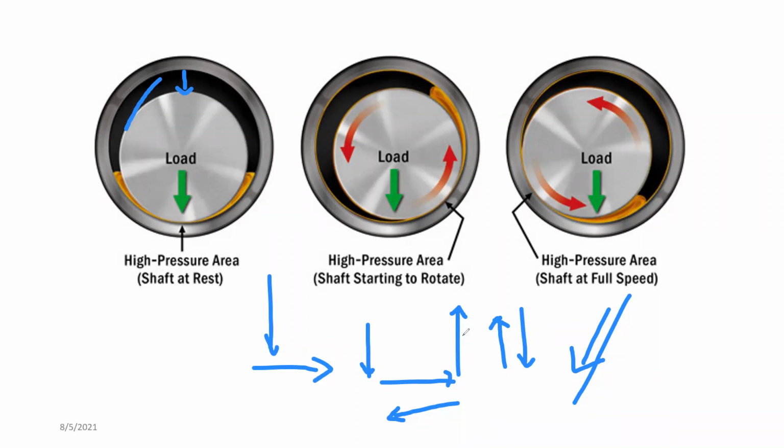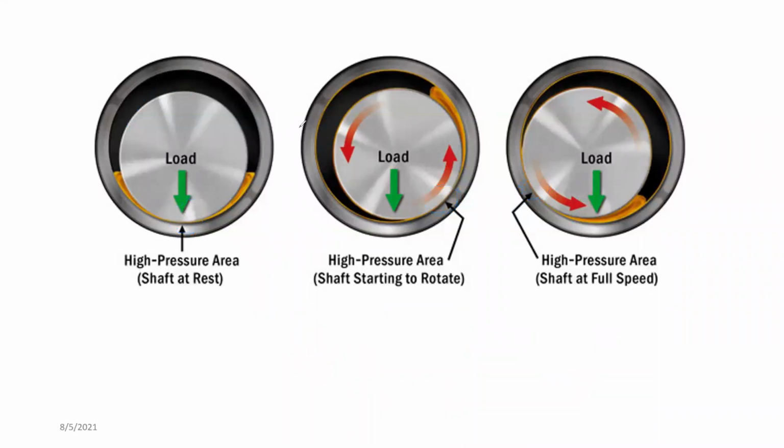This movement is cushioned by the lubrication system, and it does not allow the journal to touch the bearing itself. If you look clearly here, there's no contact between these. There's always a small gap. That's how the hydrodynamic lubrication system actually works.